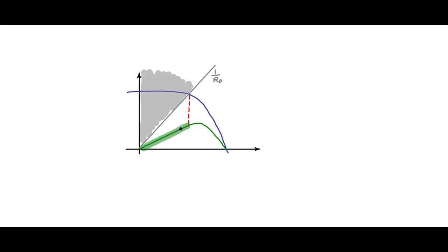Obviously the peak power point is not within the zone of operation of the boost converter, so it will result in an operating point which is not reachable. Therefore, in this case, the boost converter, if it is used, will never give you a peak power point, and will never be able to utilize to the fullest extent the PV module or the PV panel, as the converter cannot give an equivalent load line which will match the peak power point.